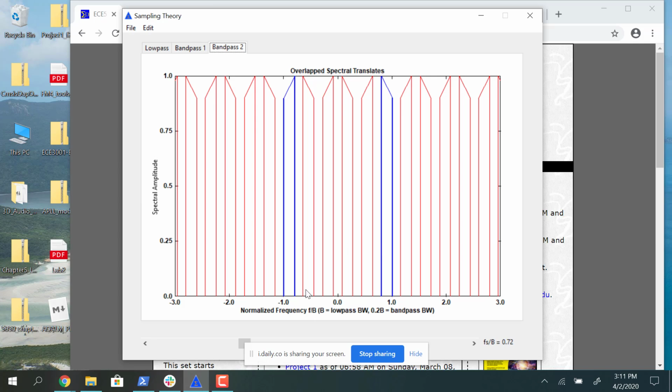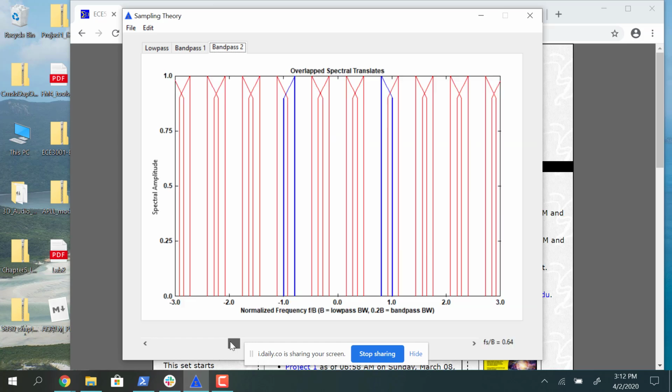If we just simply multiplied, as in coherent demodulation, to try to bring it down to baseband, we would take the negative spectral image and bring it up to 0, and the positive spectral image here and bring it down, and they would be on top of each other and flipped relative to one another, and in general that's going to be a failed operation. So it's a two-step process, but you're just looking at the first step.